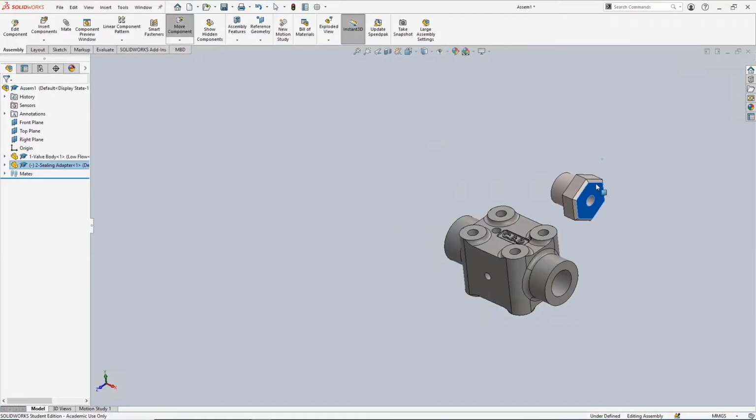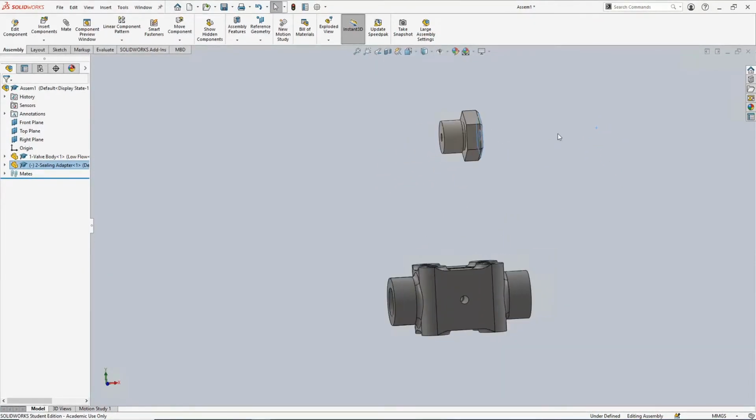But I'll try to drag and drop the second component, which is in floating state, so I'm free to do that. So I can rotate the assembly and move the component, or if I just right click and hold on a face of a floating component, I can just rotate it. So it's just rotating the component. I'm not rotating my view angle, just rotating the component with respect to the assembly planes and origin or any other fixed components in the assembly. So this is not manipulating the view. This is actually rotating the component in the design space.